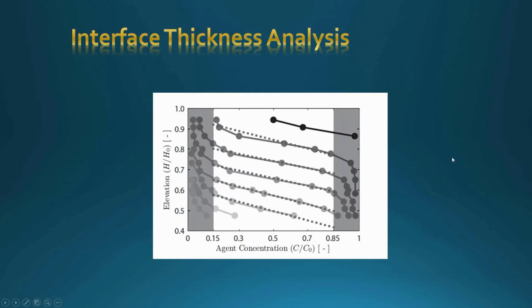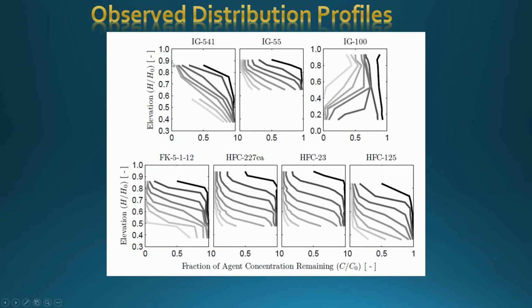It's a little bit arcane, and these are the appearance of the interfaces for the two inerts and the halocarbons, and these are the characteristic thicknesses that you can see of the interfaces. You'll notice that the halocarbons have interfaces which actually are around about 1/2 meter thick, and the inerts have interfaces which are about 1 meter thick, and that's all reflected in the new standards.